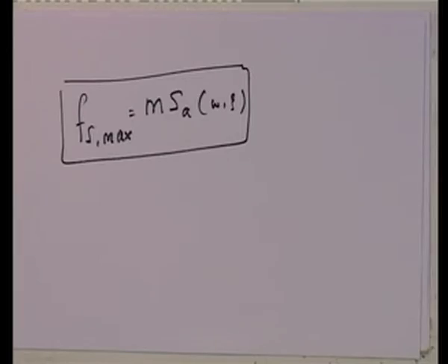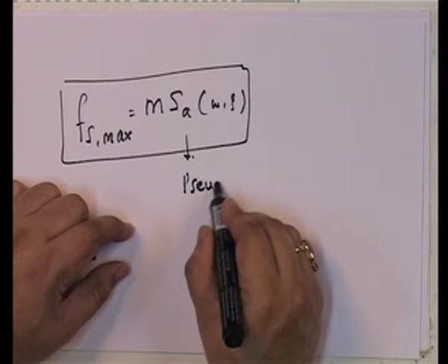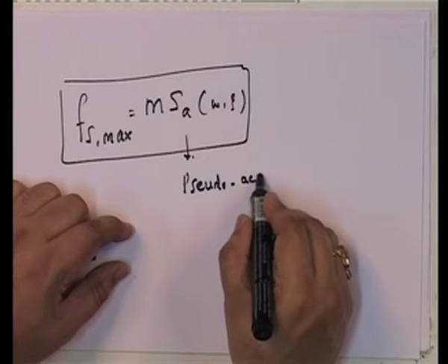So, in other words, the earthquake ground motion has been transformed, through a specific form of the response spectrum, into a mass into acceleration kind of load. So, the load is due to mass into acceleration, and of course this acceleration is a pseudo acceleration.